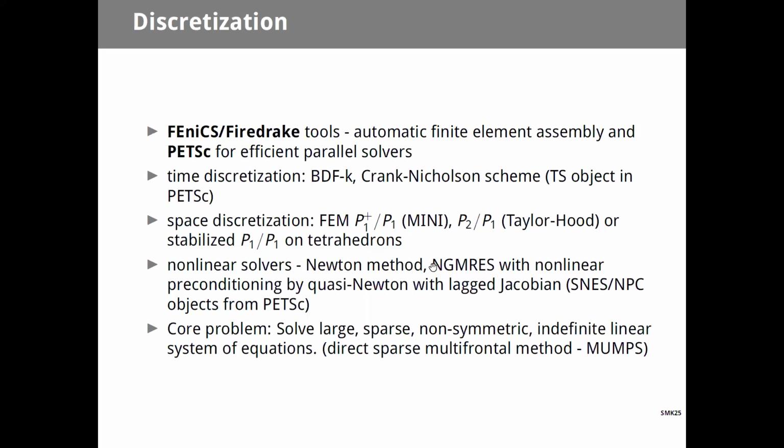In space, it's standard finite elements, inf-sup stable, so either Taylor-Hood or MINI element, or if we want in some cases to save computation or use as few degrees of freedom as possible, some stabilized P1 discretization can be used. So once you discretize it, you have a system of nonlinear algebraic equations, so some kind of Newton method.